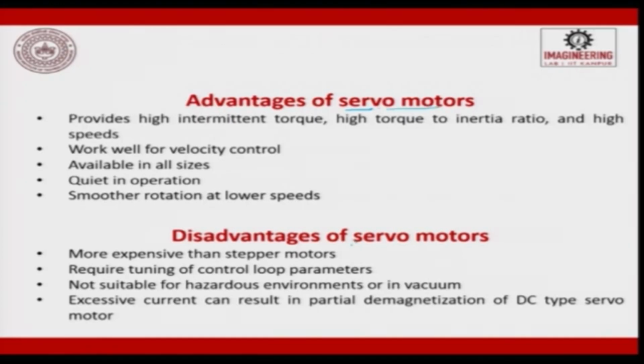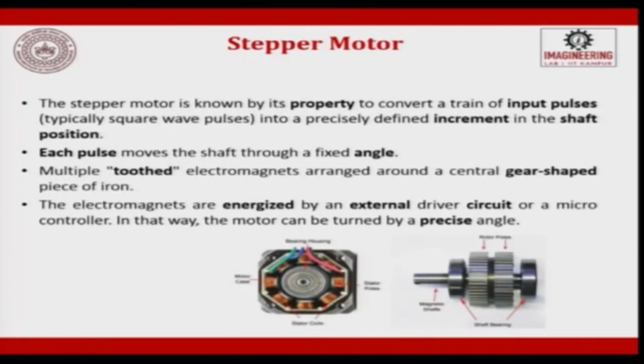What are the disadvantages of servo motor? It is more expensive, it requires tuning of control loop parameters, not suitable for hazardous environment or in vacuum. Excess current can result in partial demagnetization of a DC type servo motor. So, these are the disadvantages.